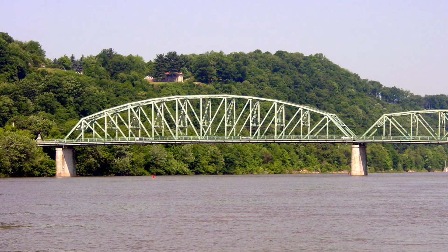So this particular truss is statically determinate, meaning that the equations of statics can be used to solve for the member forces. But one of the characteristics of that is that with this particular bridge, if you lose any one of these members, that means that the structure is going to collapse. So if you end up with a failure of that member right there, for instance, that means that the structure is probably going to collapse and fall into the river. Thus, this particular truss is non-redundant.